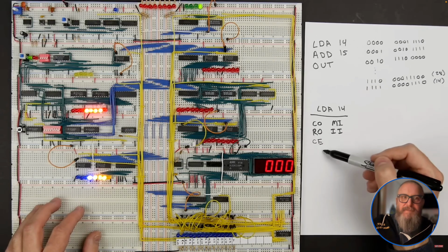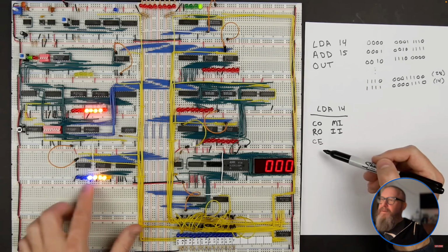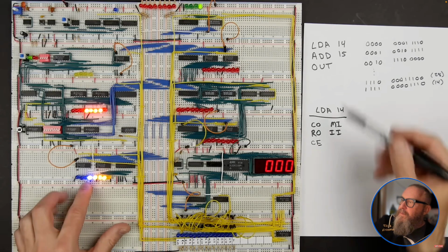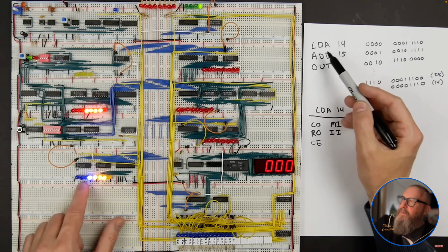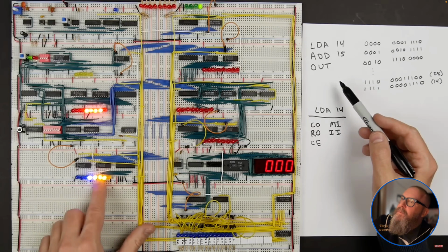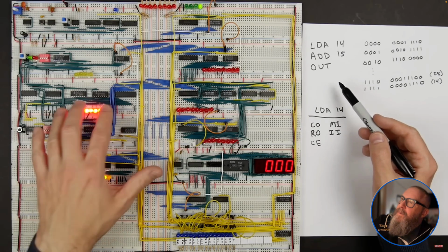Once we've done this, the next thing that we're going to do is actually execute the instruction. So now we've got the instruction. The control logic can look in the instruction register and see, okay, the instruction is 0001. What does that mean? Well, that means load A. And so the logic that we build here is going to have to take that into account and know what to do with load A. Well, we've decided that load A means take the contents of memory address, whatever this is, 14 in this case, and put that memory into the A register.